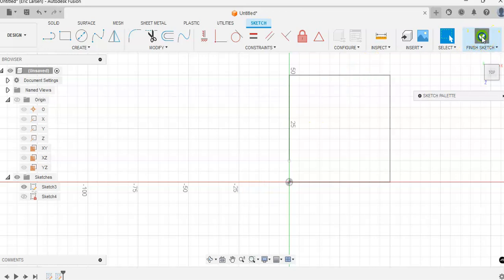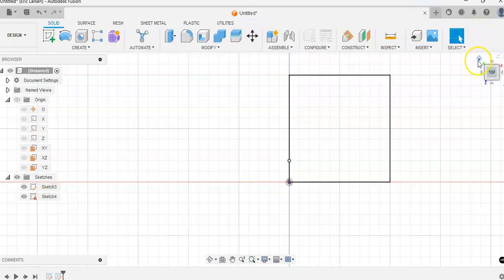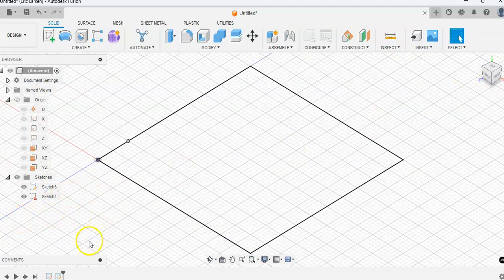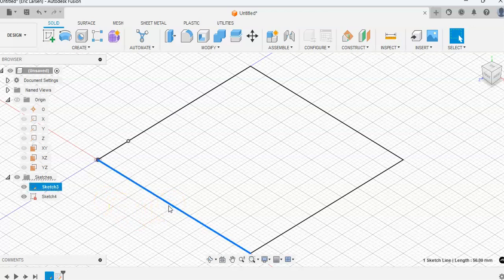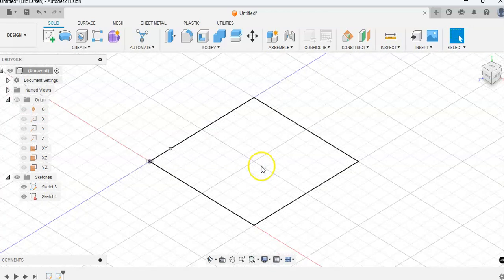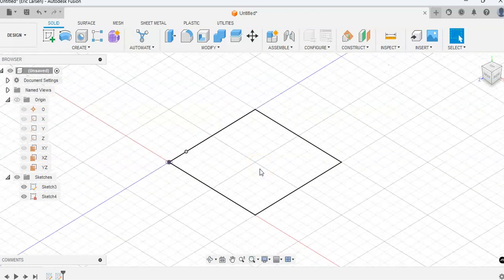All right, well, let's finish the sketch we're editing. We go back here, and we see that both sketches are visible. But if we click on things, all we can do is click on various lines, and we can't get our profile. If we click here in the middle, we don't get anything telling us that we've selected a profile. And this can be really confusing because you think, my God, it looks correct, I don't know what's wrong. But the problem is that you simply don't have a correct profile. You don't have a closed profile because you have too many sketches.